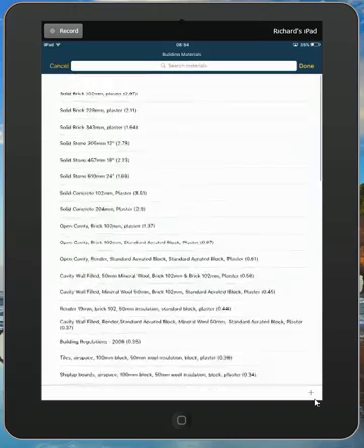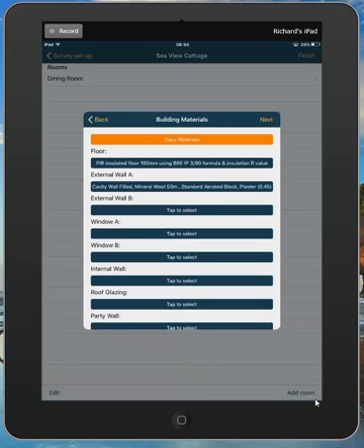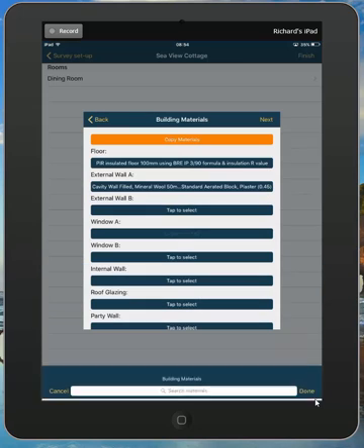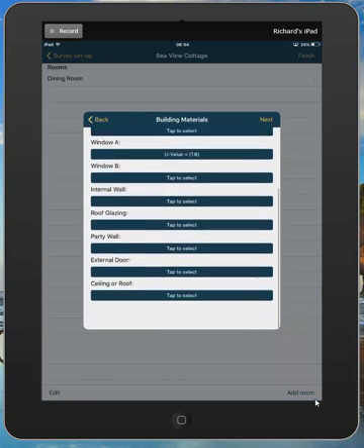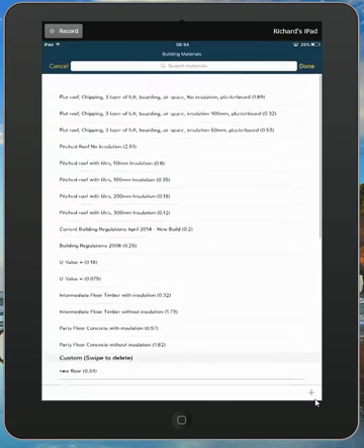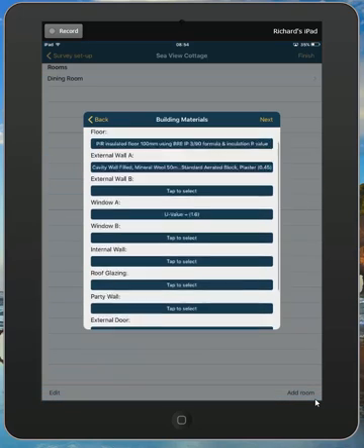So let's go to, let's say it's that window area, let's go to 1.6, and ceiling roof, let's say it's, because there's a room above, I put bedroom 1, didn't I? So let's say it's an intermediate timber floor with insulation. And so we've done all that now.